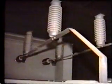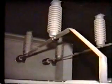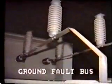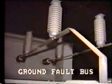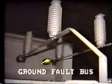Often, distribution buses are located inside metal-clad switchgear, which may be indoors or outdoors. With this arrangement, you may come across a type of bus protection known as the ground fault bus. This protection scheme is based on the idea that 99% of the faults on the enclosed bus will be to ground, that is, to the metallic structure.